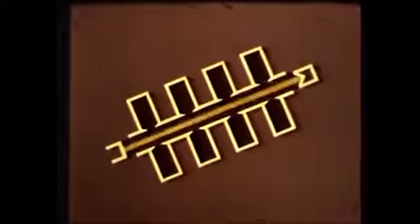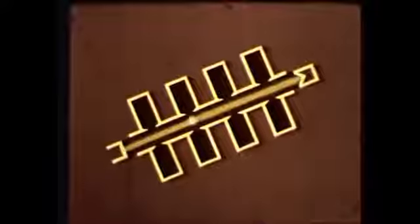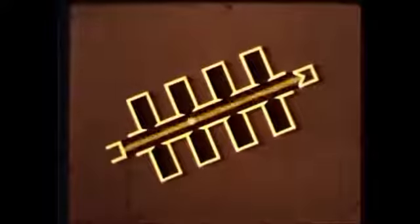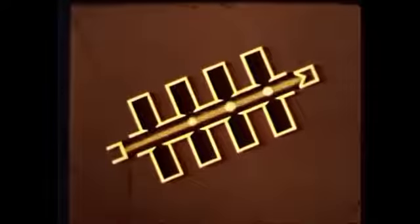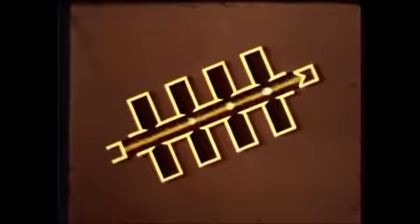If the amplification of such a two-cavity klystron is too low, then multi-cavity klystrons may be used. With a very small signal applied to the first cavity, the bunches arriving at the second cavity are very weak. But they will set up a field there which is strong enough to produce more concentrated bunches at the third cavity, and so on, enabling very large amplification factors to be obtained.